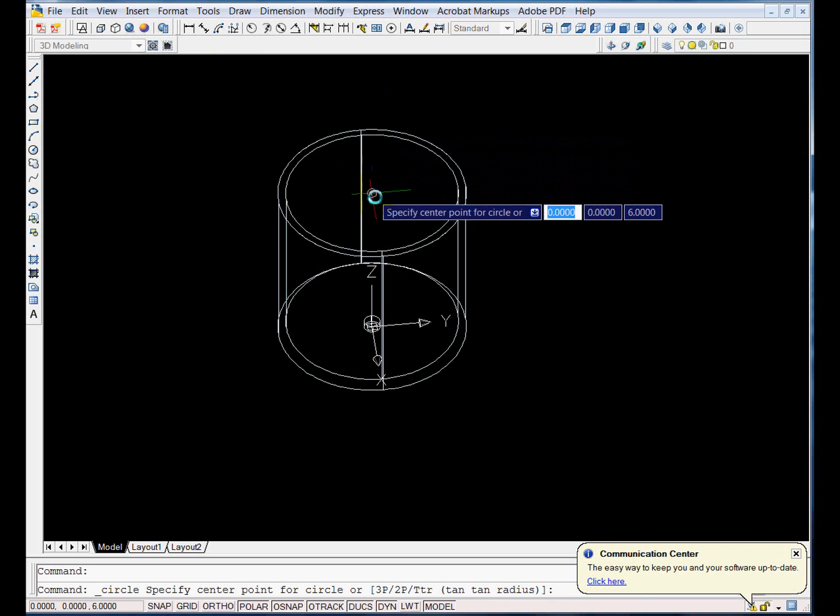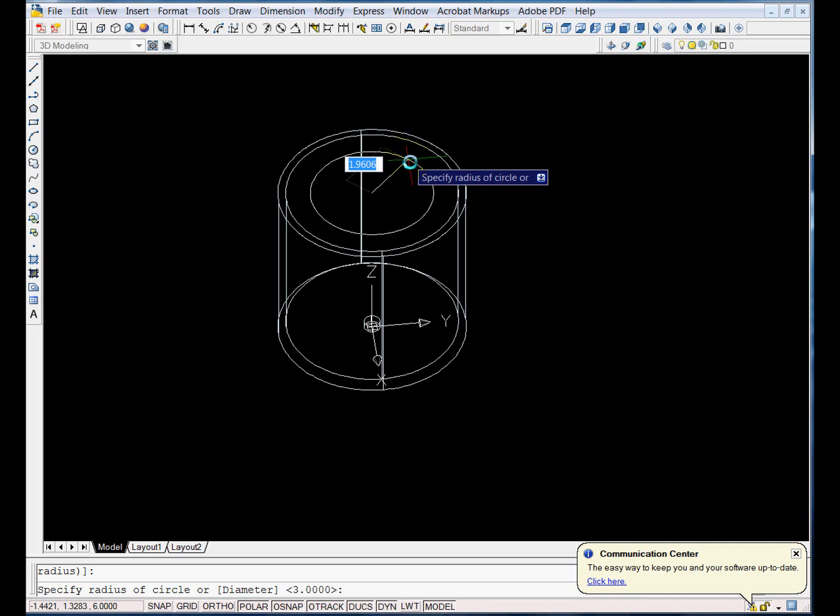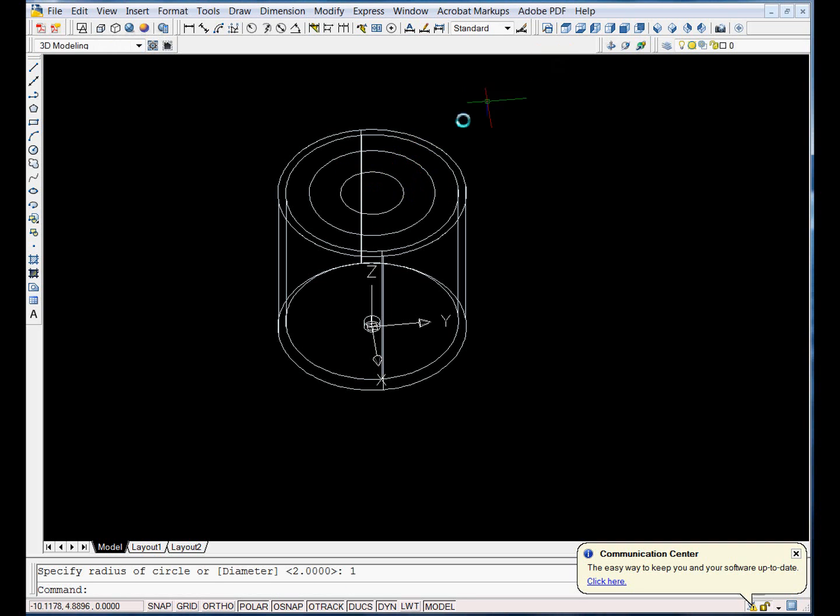And we'll make another circle here, and I'm actually going to just make a couple. So we'll do this one at 2 inches, push Enter, and then again at the center point, let's go ahead and type in 1 and press Enter. And so now what we'll do is we need to grow this. And the way that we're going to do that, we'll go ahead and inspect it, but grab the Line tool and put it at the point at the very top and put it straight up and down so it's vertical.